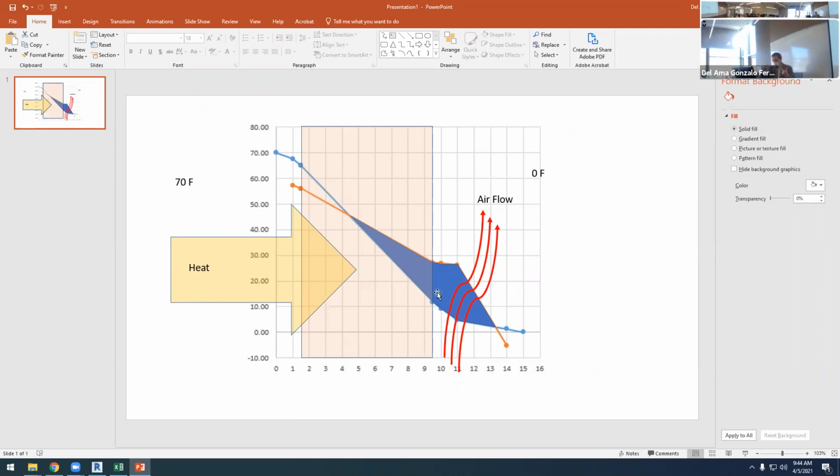But you have to think about it, and then you need to have your own criteria. If you are working with a company and you see what they are doing, and you request the vapor barrier, and you find out that 90% of vapor barriers are torn, not continuous, you can say, okay, I won't work with this company again. It's not that this happens and having vapor barriers is useless. I would make the decision of not working with that company again instead of not placing vapor barriers, which I think is the correct decision.